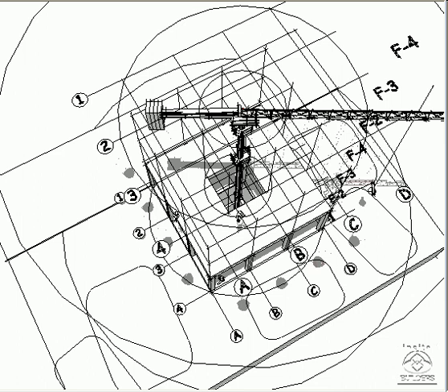Crane operators must be aware of these distances because of load limitations. And the control zones restrict operation of the crane, limiting its movement. For example, swinging a steel member across the zone would be dangerous for the management structures that are in this area, the job trailer, vehicles, other storage. On large projects, the laydown areas will also have grids. These designate the location of materials waiting for installation.